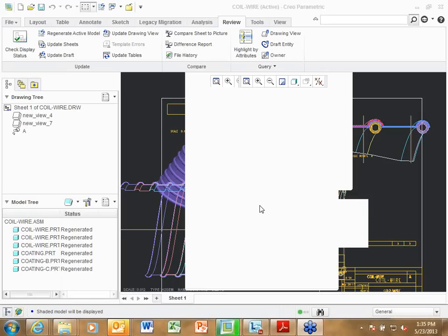So before I write that relationship, I will make sure that the assembly regenerates if I'm changing one of those variables called pitch or diameter, whatever that range is. Now, in some cases where it doesn't, you'll know where those ranges actually are, and you have to know those situations. When I'm changing variables like this, I want to know where I can recover all the time. And that's what we call massaging the model.